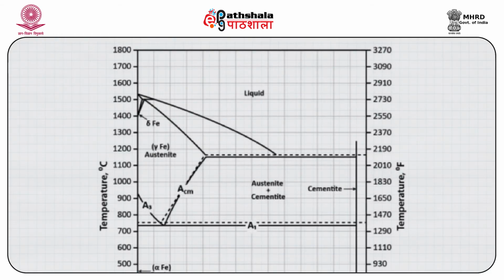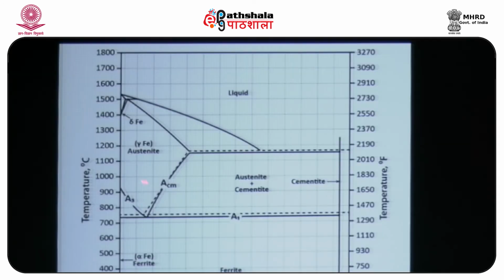What it says is the easiest way to read how phase changes happen. Say, for example, you look at 5 weight percent of carbon and 1000 degrees Celsius. It intersects somewhere out here, so it would be mostly austenite and cementite. Basically, these are the different forms of steel.